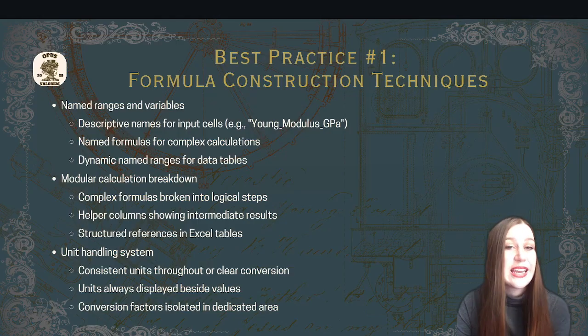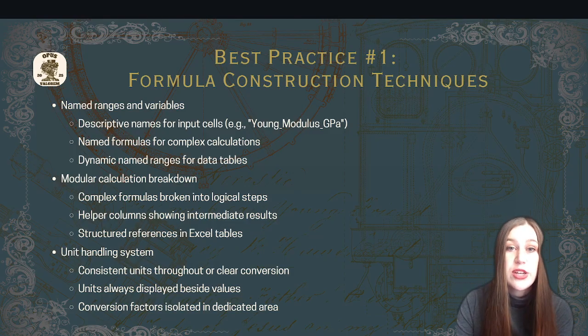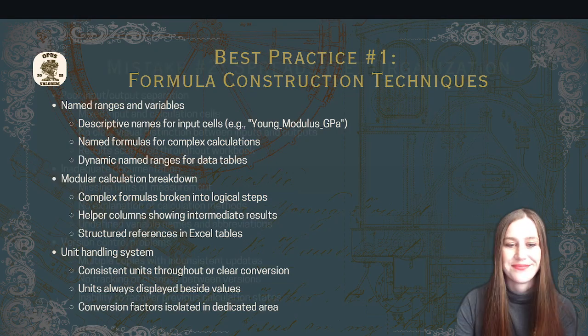Then, on to handling units. Use consistent units throughout your CalcSheet with clear conversions worked in. Always have the units explicitly noted next to the appropriate values and keep the conversion factors isolated in a dedicated area. This reduces user-imposed errors.